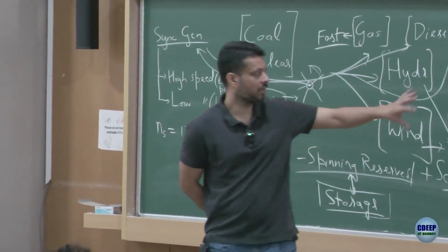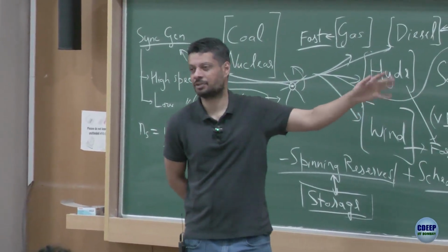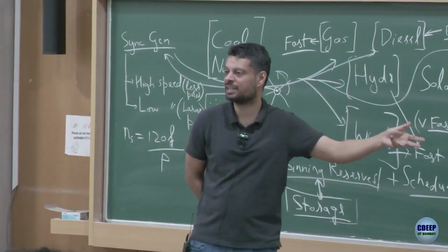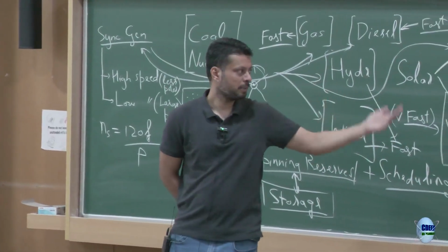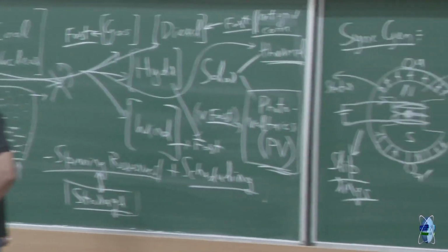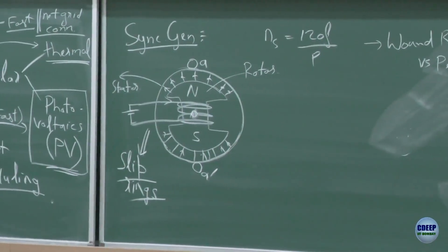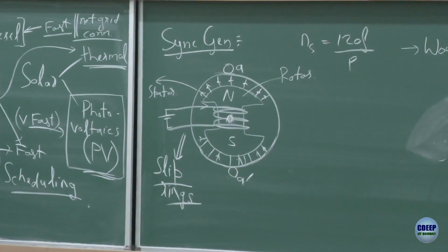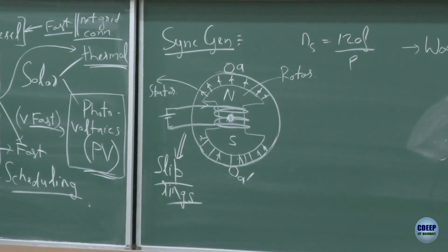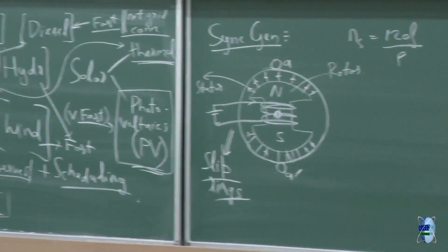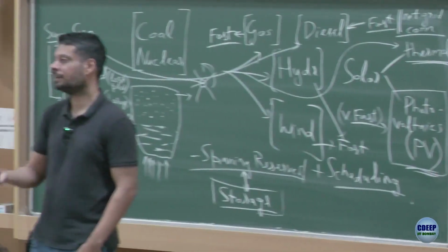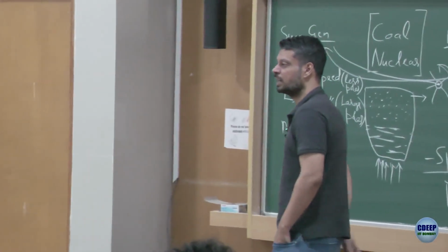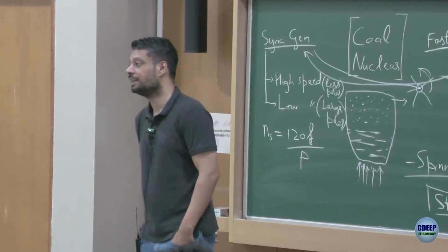As I am rotating the rotor in any direction, clockwise, anti-clockwise, with a constant speed, what will be the voltage induced in the one turn of the stator? Single turn. Sinusoid? Okay, why do you think sinusoid? Yeah, but anything can be changing. It's not only sinusoid which changes, right? You can have a triangle wave, you can have a square wave, you can have n number of shapes which can be produced because of the changing field, right?